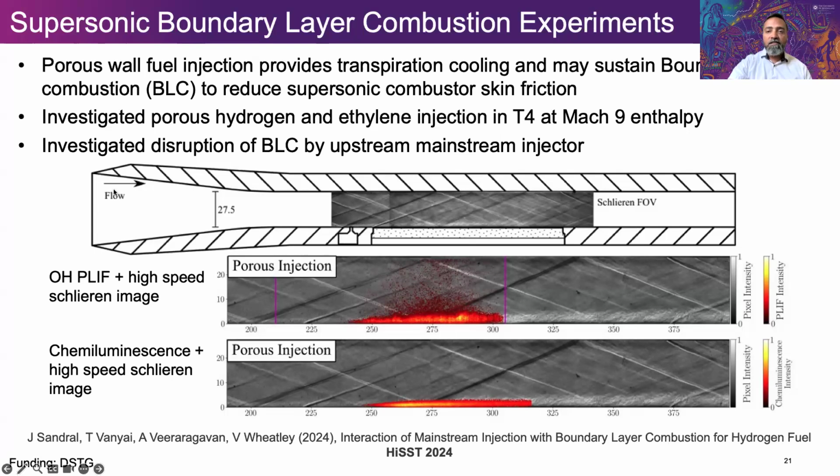A lot of the other international community that does work in experimental hypersonics, particularly in scramjet research, shy away from injecting fuel up in the inlet because they're worried about what happens if that causes this undesirable phenomenon, which I'll talk about at the end, called unstart. So we embrace that as an opportunity, not a negative. So we try to inject fuel upstream.